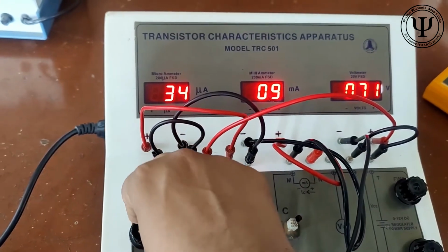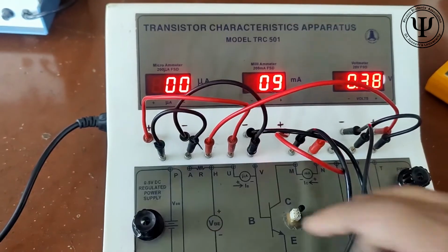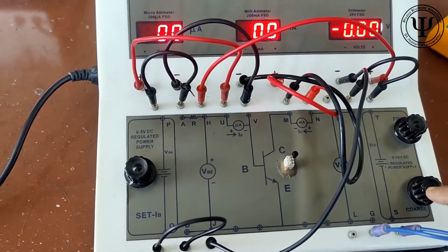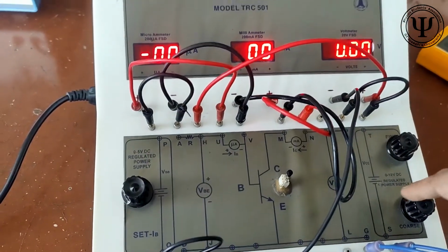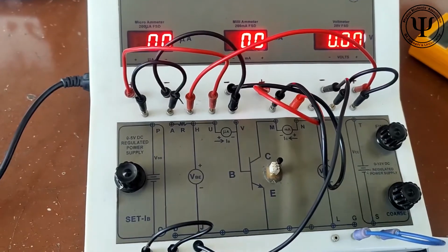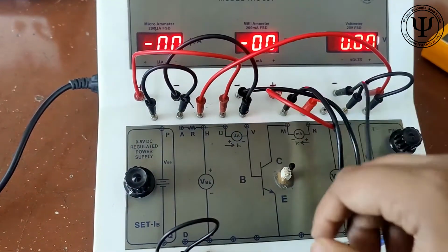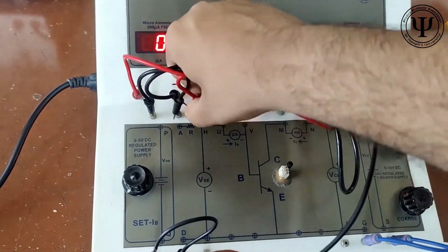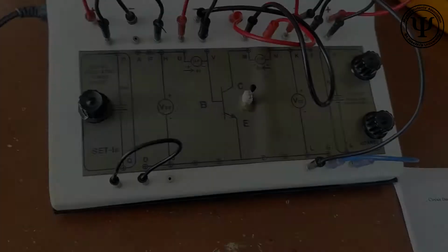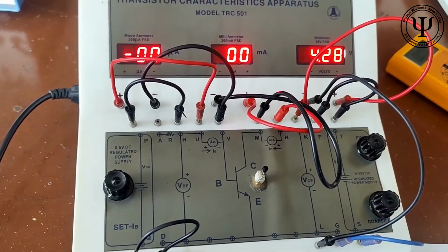And again do the same experiment while changing VCE to 8 volts. We did this experiment for VCE equal to 2 volts. Now in order to change it to 8 volts, you have to do nothing but take these VBE points out, and now change this to 8 volts.